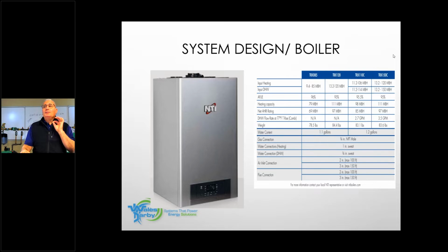That's really important. Another really key feature about NTI condensing boilers is we have a boost function built in. A lot of times we go out to jobs and we see these boilers installed and the outdoor control is not connected to it. The wire's just hanging next to the boiler. The reason is the contractor replaced a cast iron boiler, put this in, set it up for outdoor reset with all the good intentions, and the homeowner is used to being blasted with a lot of heat from their old system, so it doesn't feel the same. So there's two things we have to do, guys. We do have to educate them as to how the boiler is going to react. Do you feel comfortable in the room? Don't be fixated on a number on the thermostat.